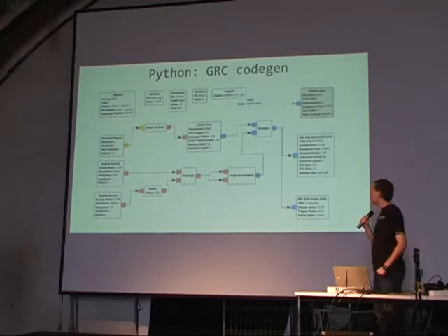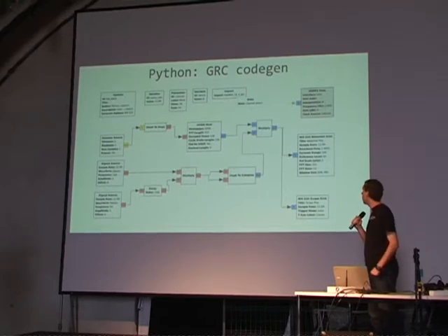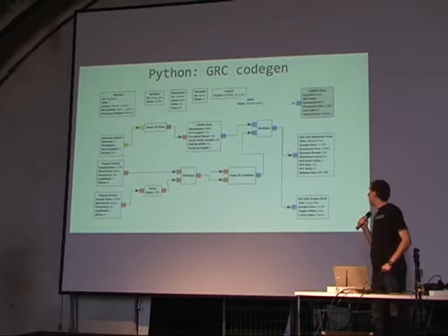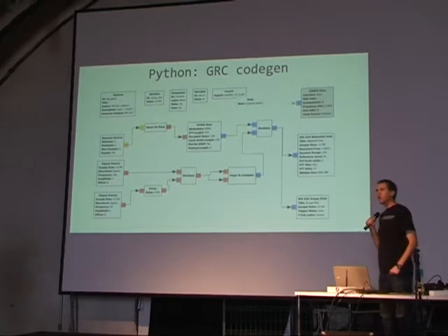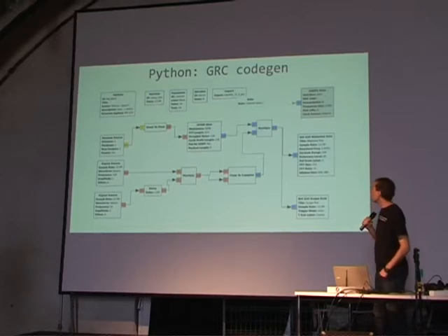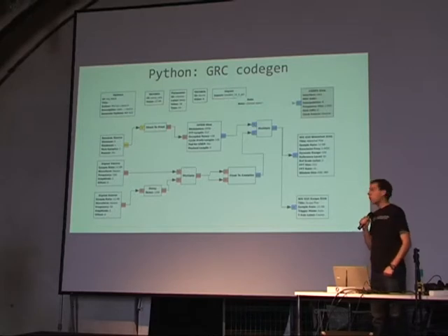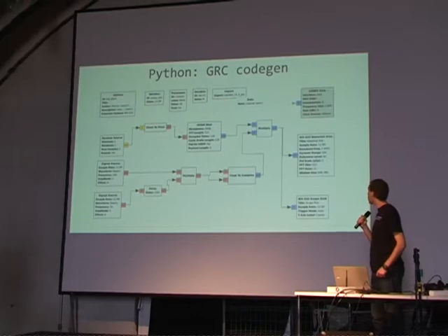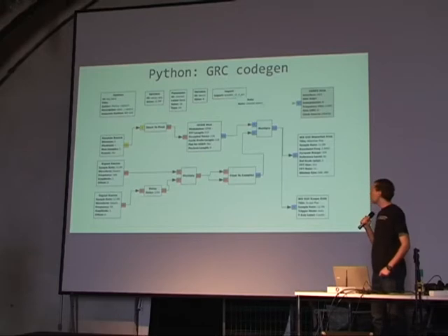And this parameter here defines a channel, and since IEEE 802.15.4 has, I think each channel is 5 megahertz. I think there are 11 or 12 channels, something like this. But at least, no, there are more channels, but it starts at 11 and goes to 26. So each channel corresponds to a frequency that is automatically set at the USRP2 sink. I've used an OFDM modulation, while OFDM is used here to do an interference simulation.